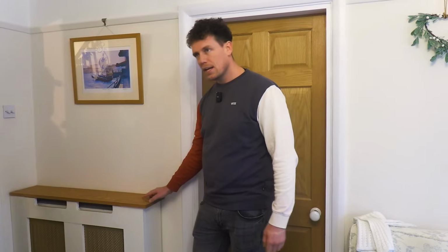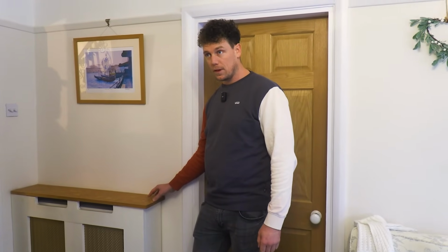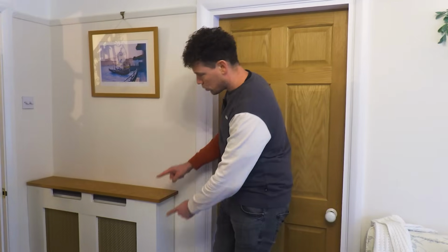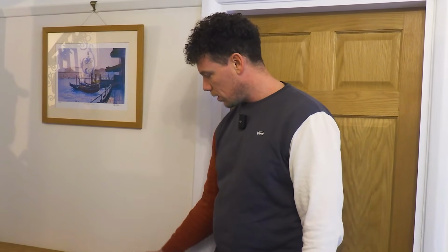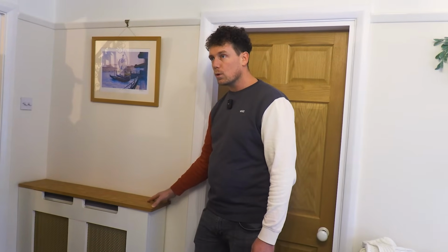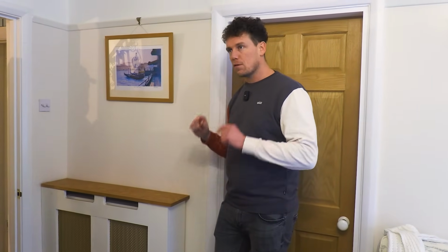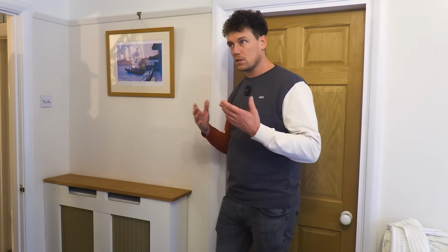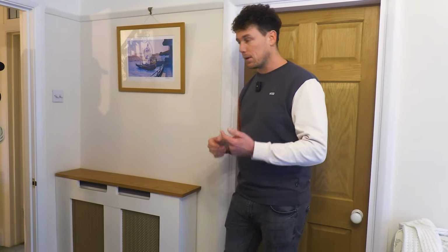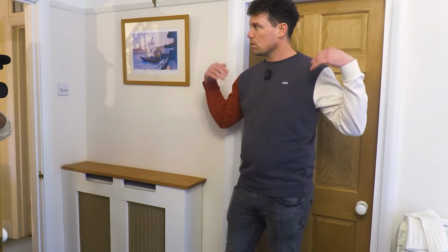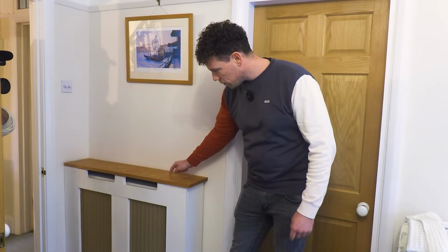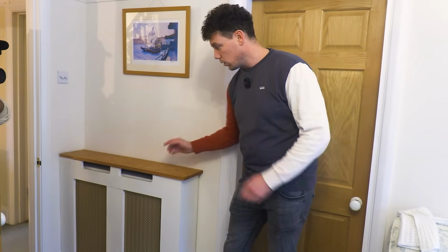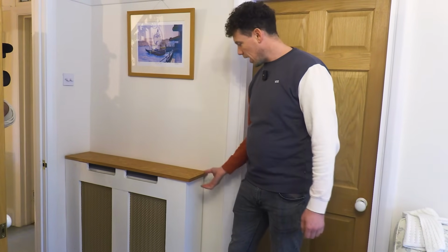Because these hinder the convective effect of convector radiators, i.e. where it draws in cold air and allows hot air to shoot up, much like a chimney, they lower the heat output of the radiator by around 5%, which sounds small, but when it comes to dictating your flow temperature, which is what gives the efficiency of condensing boilers or heat pumps, it's actually quite a remarkable difference. This room, as you walk in, it feels colder. That cover is why. You've got a big treble convector radiator underneath here, which would create quite a lot of updraft had it not had a lid on it.